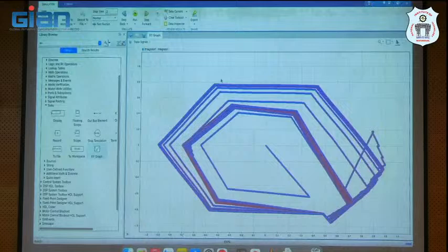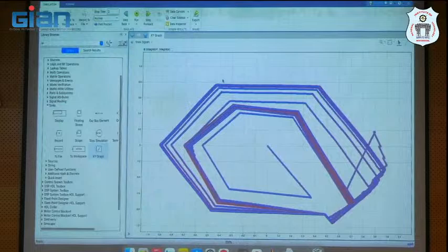Then only we can produce unidirectional torque. This is very important. If you want to produce unidirectional torque, your magnetizing flux should be sinusoidal. Your magnetizing flux must be rotating in a circle. If you start your sector number from 0, this is the nature of magnetizing flux, right?